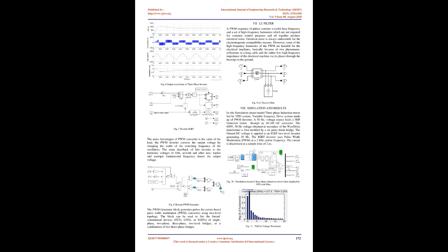Power inverters are the basic electronic circuits used to convert DC to AC. The inverter input may be from rectified AC input or a DC source. The categories of switching for the inverter are the square wave and pulse width modulated techniques. Fig 2 AC/DC/AC converter. 5. 3-phase rectifier. Full wave bridge rectifiers are used, employing either silicon junction diodes or thyristors, because of the arduous operating conditions in a power station and the need for maximum reliability in life.